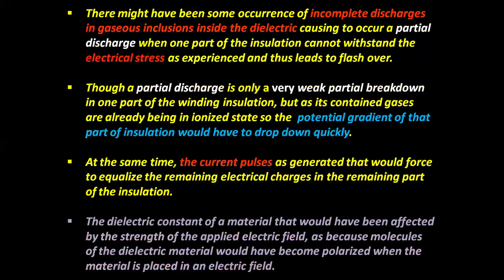There might be some occurrence of incomplete discharges in gaseous inclusions inside the dielectric, causing a partial discharge when one part of the insulation cannot withstand the respective electrical stresses as experienced, and thus leads to flashover.